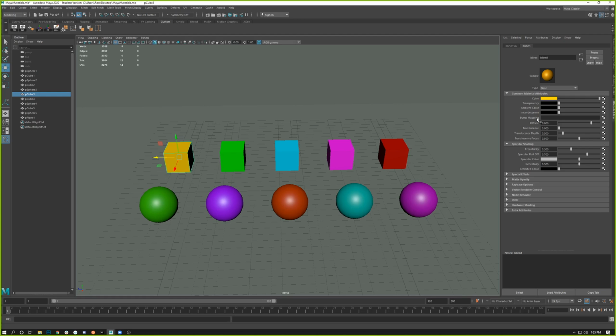You can turn on incandescence, give it a color, and it would glow and emit light. Again, I don't think the default settings are like that, so I'd have to cover that in a rendering video, but for now that's what incandescence does. For your case, without setting up that render, you could fake incandescence. But other than that, I wouldn't recommend it until we cover more rendering in detail.